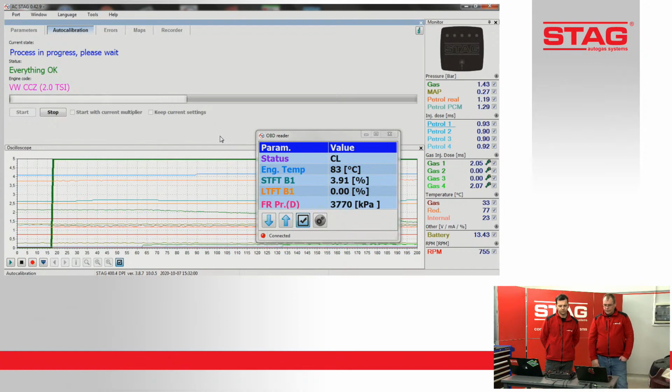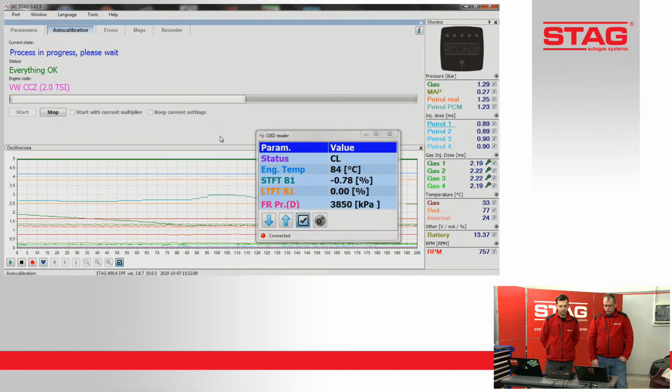Yes. In terms of gas injection, every time that's 2 or above is good. The shorter times, let's say 1.8, 1.7, are a way to think that something can be wrong on the cables, on the connections.